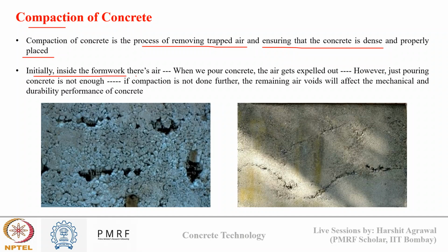Now, initially inside the formwork there is air. So suppose there is an empty formwork. There is air inside my formwork. Now, when my concrete is poured, my air gets expelled out. However, just pouring of concrete is not enough. If compaction is not done further, there will be air voids remaining inside my formwork and in between my concrete, which can affect the mechanical and durability properties of my concrete. And how this affects the performance, you can see in the images.